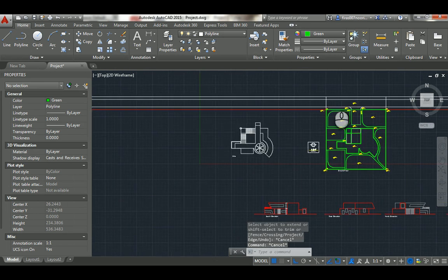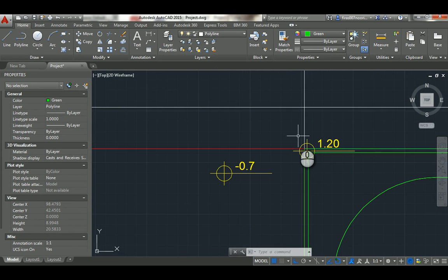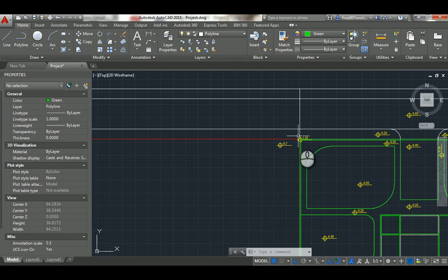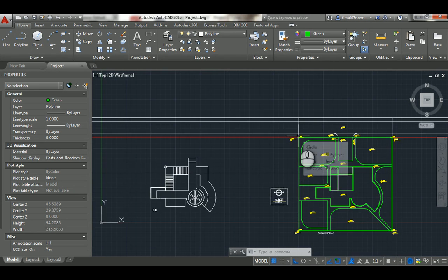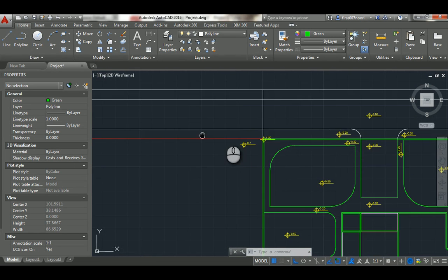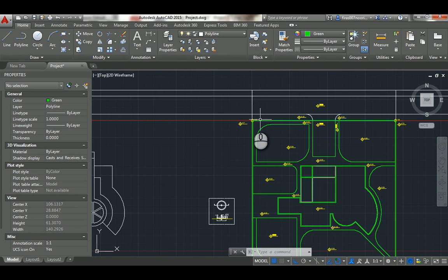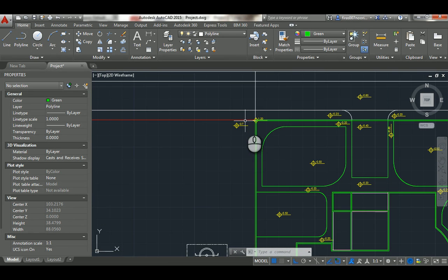I kept this line, so I can later on just pick points here if I want to make the level of the street change. So if that is not the curb, and is not minus 0.2, maybe you put something else in here. You can control that by adding an extra point here in vertex, and then inside 3D Studio Max change the height of those vertices here to make the street slope with the slope of this curb.